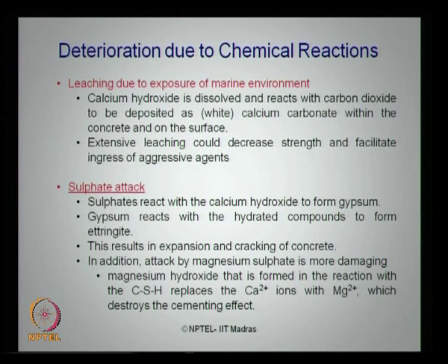Calcium hydroxide is dissolved and reacts with carbon dioxide, forming a white deposit of calcium carbonate within the concrete and also on its surface. Extensive leaching could decrease the strength of concrete and also facilitate ingression of aggressive agents into the concrete, which then further react with the rebar embedded in concrete and cause corrosion.